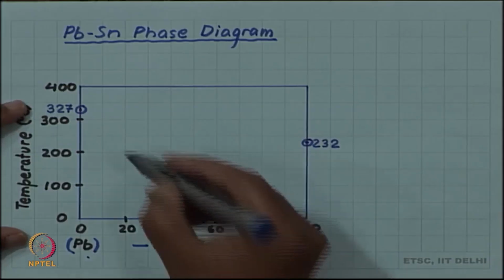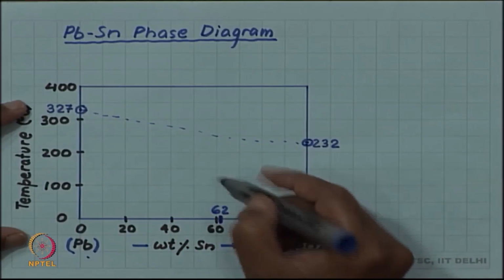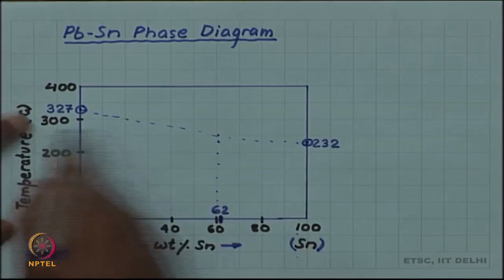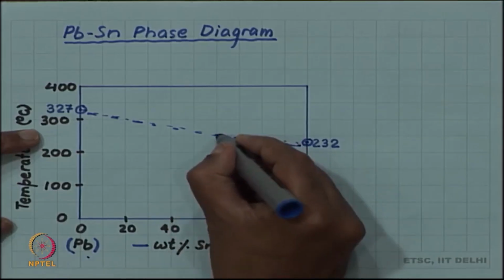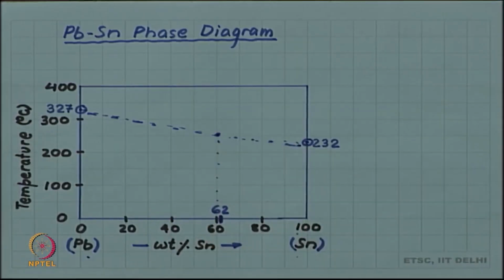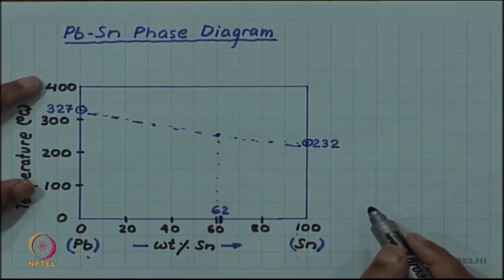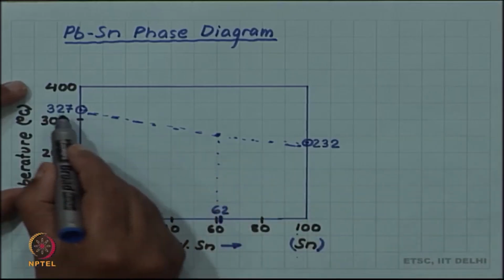we have already seen that our first approximation, which was a linear approximation, was not very right. My line is not very straight, so excuse me for that. Maybe I will try something better this time. So, if I draw a straight line and if I try to predict a melting point, I get something close, but that is not the truth, because now you know better that for alloy the melting is not happening at one unique temperature, but over a range of temperature.